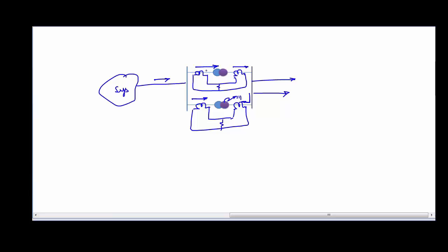So since there is a flow of current through this particular CT, in order to balance that, there will be a flow in the secondary of the CT, and it will have this particular direction. And for this side, the current will be flowing in this direction, and we can see that in this transformer's differential relay, means this relay, the currents are flowing in these two opposite directions,